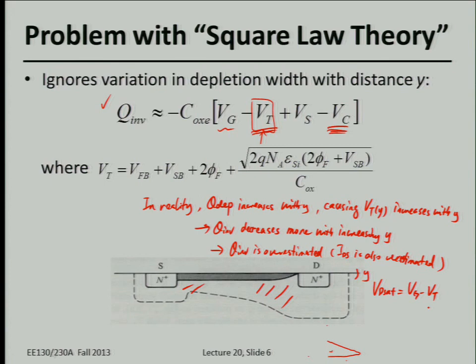So in other words, in reality the saturation voltage could be even smaller than this value, because you underestimate depletion charge. If you take this effect into account, you're going to have the pinch-off region appear earlier in the channel than in your approximated models, right? So the consequence would be that in reality the saturation voltage would be lower than that value. Okay, your MOSFET is going to saturate earlier.